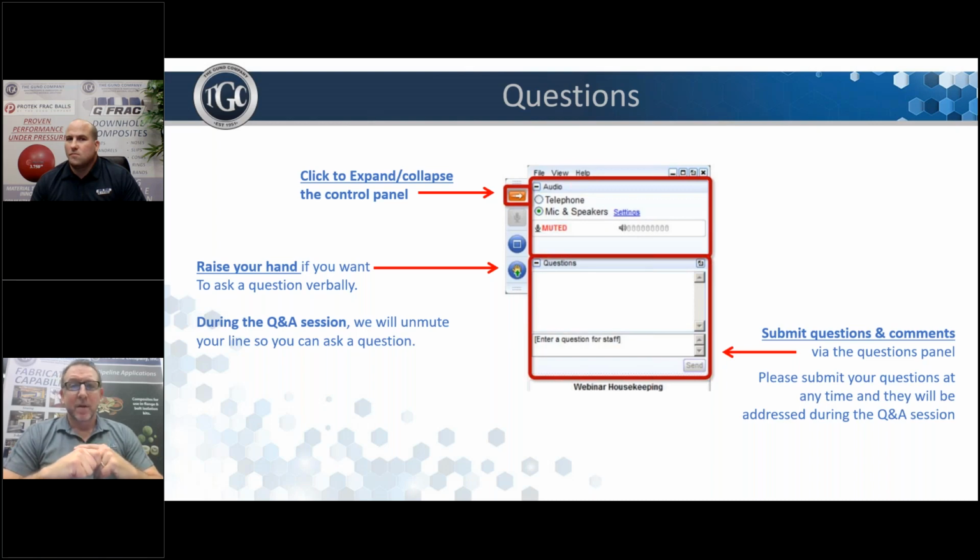If you have a well that doesn't get that hot, and you can bring the temperature of your resin system down, you're going to be getting into some softer resins. Essentially, your drill out time will get better if you use a little lower temperature resin. So I hope that answers your question,